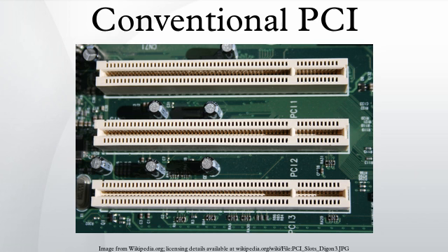However, some 64-bit PCI-X cards do not work in standard 32-bit PCI slots. Installing a 64-bit PCI-X card in a 32-bit slot will leave the 64-bit portion of the card edge connector not connected and overhanging. This requires that there be no motherboard components positioned so as to mechanically obstruct the overhanging portion of the card edge connector.